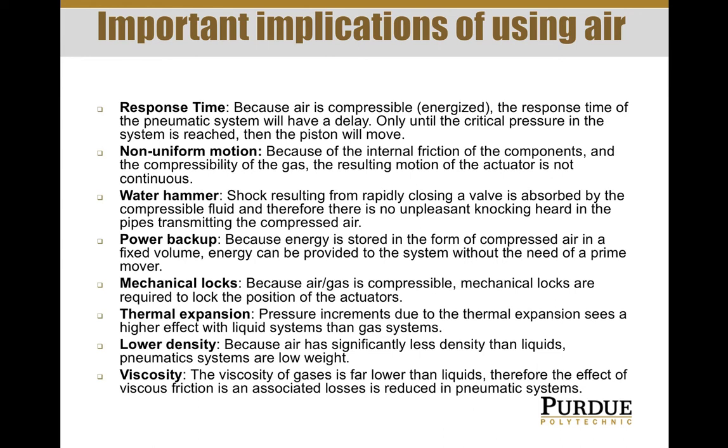Another disadvantage of compressed air is you need to use mechanical locks if you want to keep the position of the piston or the rotary actuator locked. You need to lock it with mechanical systems. You cannot, like in hydraulics, simply close the valve and then assume that the cylinder is going to stay in position. That only happens in hydraulics. You cannot do that with pneumatics because pneumatics are compressible.